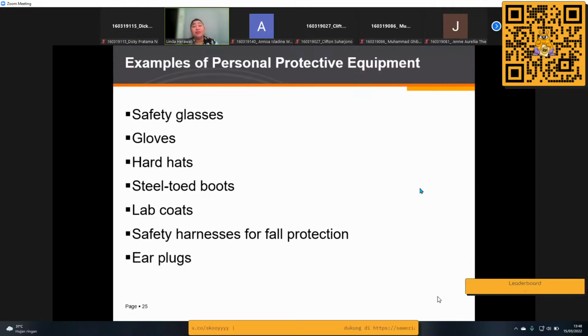And then the third level for the mechanical hazard and safety guards: when you cannot design the safe machine or safeguards, you go to the next level. You have to provide all of the personal protective equipment. For example, you have to provide safety glasses. If there is so much fire, or so much dust from the industry, you have to prepare safety glasses for your workers and yourself.